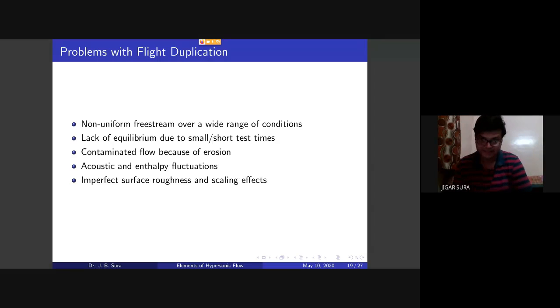And scaling effect. Say there is a wire or an antenna from the nose of the plane, I'm talking about a normal subsonic Airbus, to the rudder section of the plane, which has a diameter of 10 mm. Let us say 10 mm is a large size, but let's say it is there. If you want to scale down 1 by 10, it will become 1 mm. Now a 1 mm wire will have a different effect than a 10 mm wire. So scaling will be a problem.